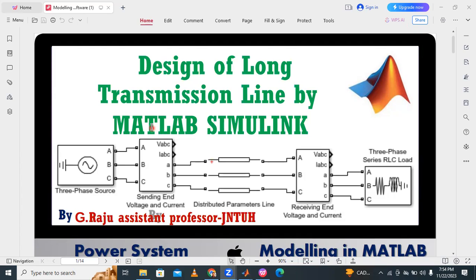First, in this MATLAB Simulink, we have to take a three-phase AC voltage source. This is for the source side, and on the source side one measurement is required: voltage and current measurement, a three-phase VI measurement. Sending end voltage and sending end current can be measured by using this three-phase VI measurement. This is called the sending end side.